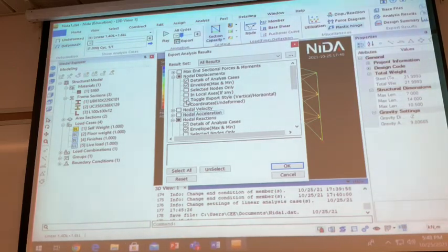This is a rectangular frame, so you need to apply the load force. For example, I have the frame here. When you apply the load force at the top, you can read the local displacement and put it in this formula, and this is the total height. When you put the load at the second floor, the height should refer to the second floor, and the lateral displacement should be at this floor. Then you can calculate the critical load factor.